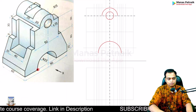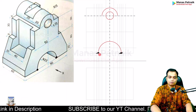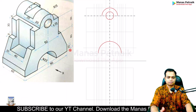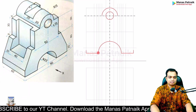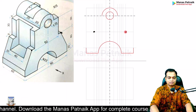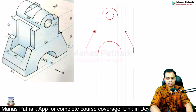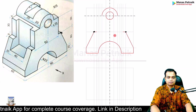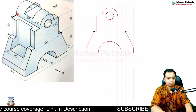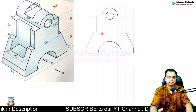Now, please match the points. Yes, sir. Please match the points again. Okay. Left, right, left, right. Enjoy the process. Then go up by 10 millimeters. Done. This is the point. These are the points. Join. Done. Then move towards left 5 millimeters. 5 to the right, and here 5 to the left. Done. Then move upwards by 30 millimeters. And then straight away join with this semicircle. Done. The front view is done.